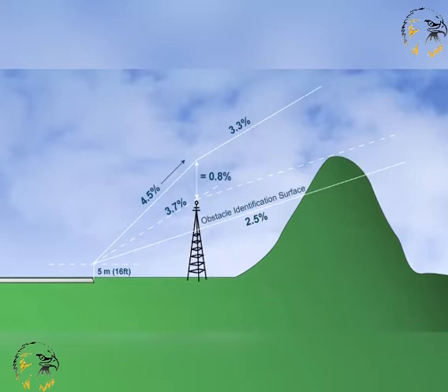Published gradients will be specified to an altitude or height, after which the minimum gradient of 3.3% is considered to exist. The final PDG continues to exist until obstacle clearance is ensured for the next phase of flight, en route, holding or approach. This is when the departure procedure is defined to end.